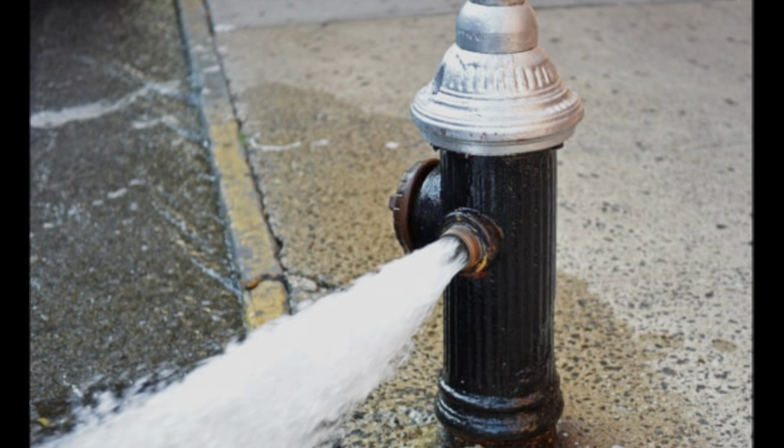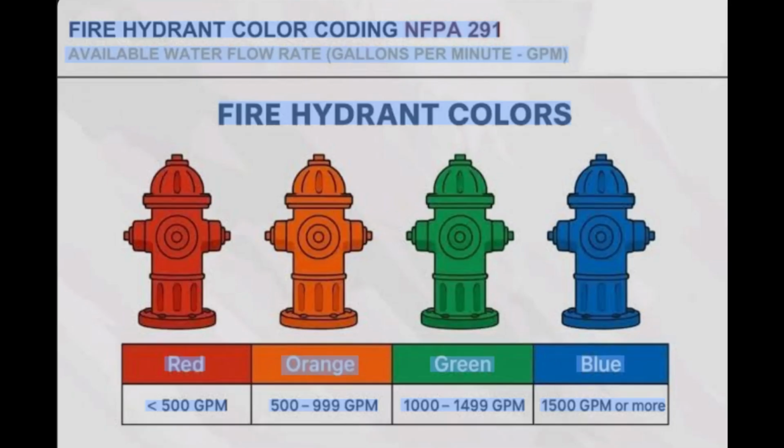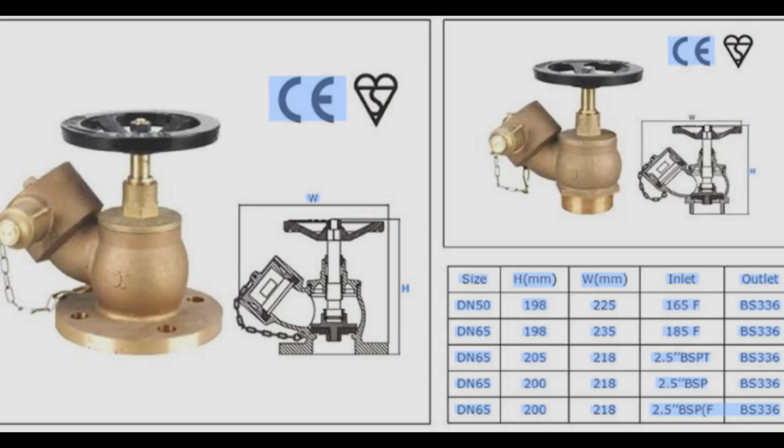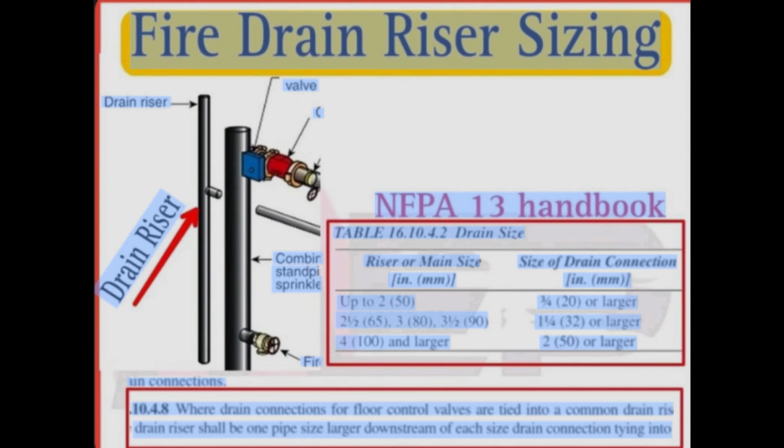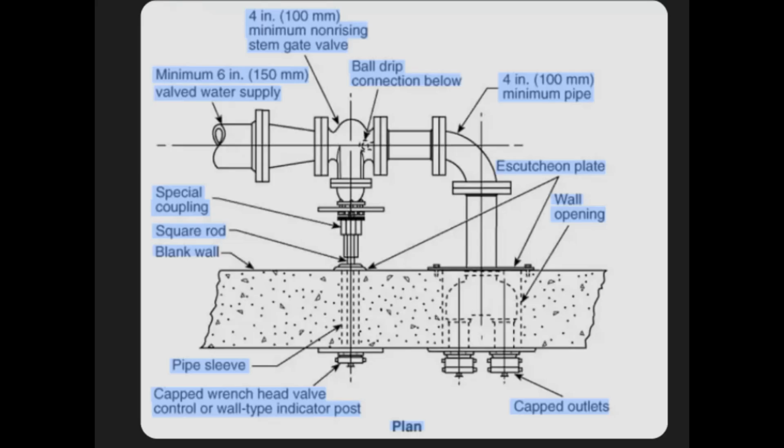6. Hydrant and standpipe data. Typical values: hydrant flow, 946 liters per minute. Landing valve pressure, minimum 4.5 bars at top floor, standpipe class 3, riser diameter 150 millimeters, hydrant ring main 150 millimeters. These ensure firemen have the pressure and flow they need.